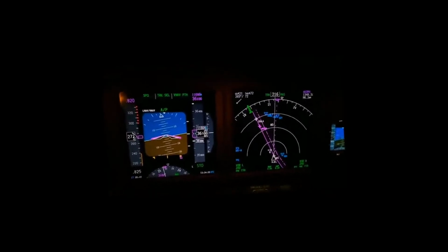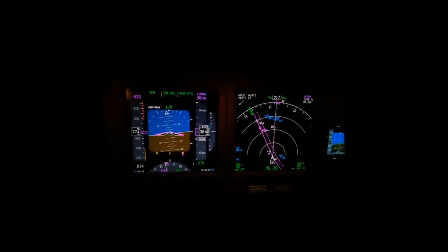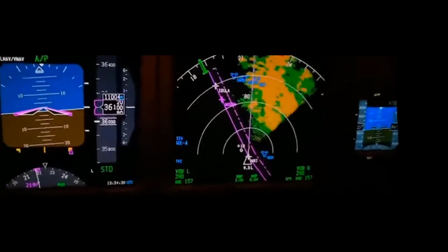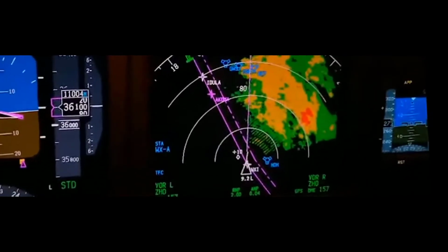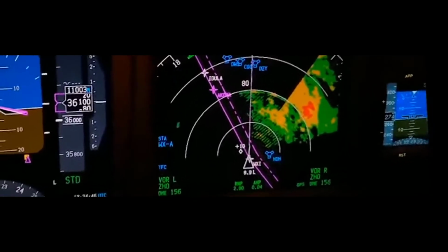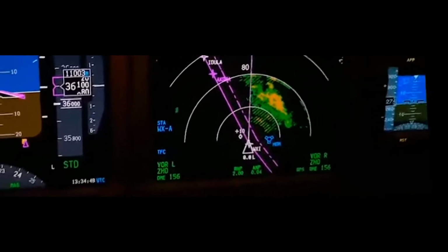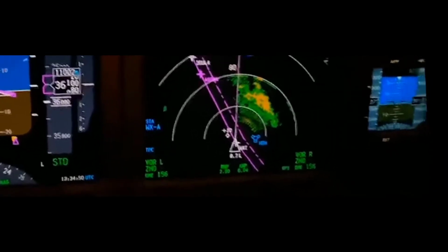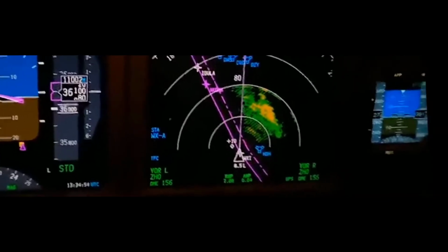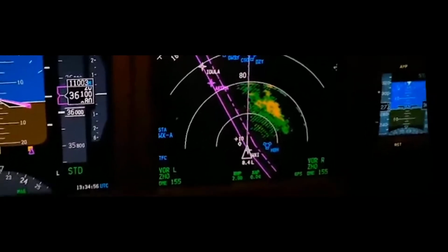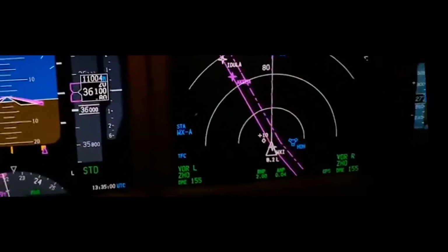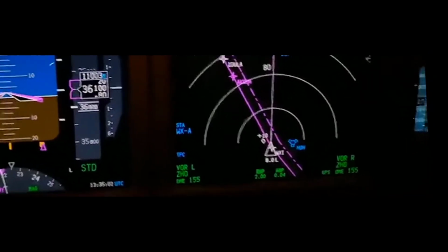This occurs when the receiver and transmitter lose lock and do not track with each other. This will typically appear on a radar display as a pie-shaped patch and will only be present if there is weather to be shown. However, with newer radar systems like the RDR-4000, the most common cause of spoking comes from the antenna and is caused by noise from the sweep resolver, damaged waveguide, or malfunctioning rotary joint.